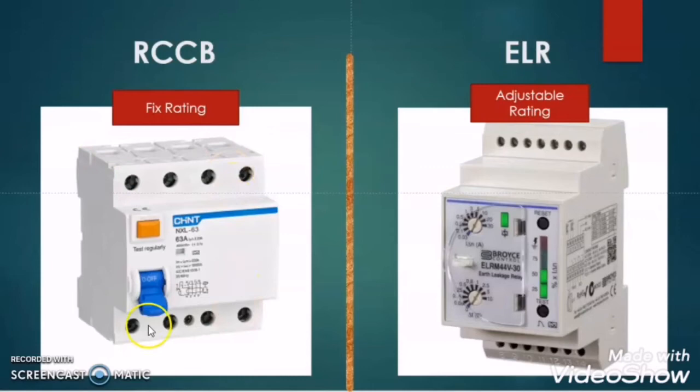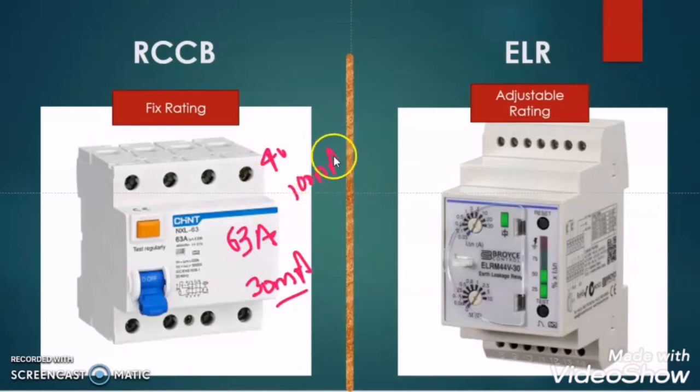Suppose we purchase this RCCB and it is a 63 ampere, 30 milliampere sensitivity rating. We cannot change this RCCB to a 40 ampere, 100 milliampere RCCB because its rating is fixed. We cannot change its rating.